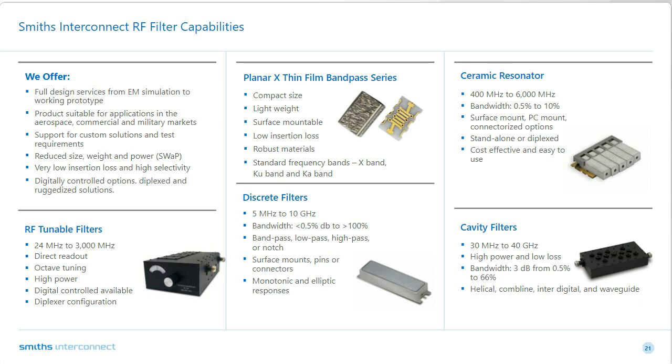Photolith has over and under cutting when etching. What can you achieve? Well, it kind of depends on the metal stack up and how thick of a metal you use. There are ways to control it by annealing the metals, to avoid some undercutting. There are other things that can be done as well, but I can't give an exact answer just because it depends on the overall thickness.